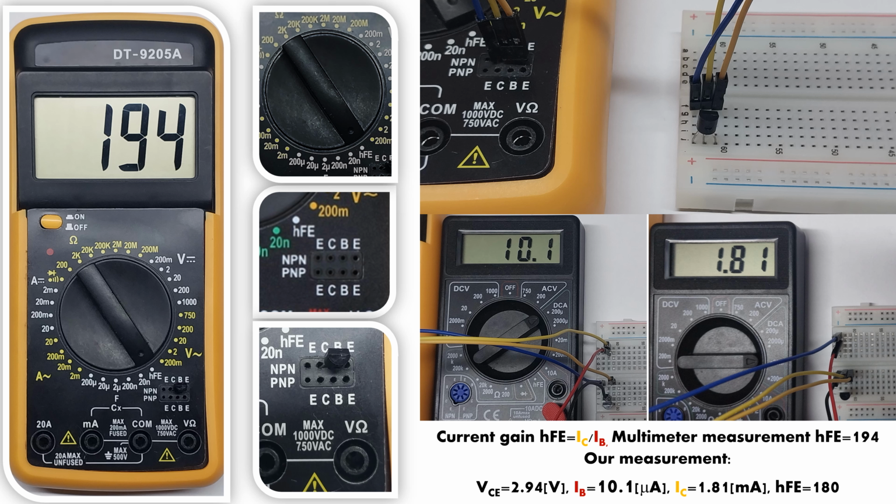In summary, to measure hFE parameter of a transistor, we use the hFE port on the multimeter, and choose hFE with the dial selector. Using the datasheet for a specific transistor, we identify and orient terminals, so they match slots on the hFE port on the multimeter. When the transistor is inserted, and the multimeter switched on, the display shows the measured hFE value. By means of replicating the hFE port from the multimeter onto the breadboard, we have been able to measure values for VCE, base current, shape of base signal, and verify our measurements by measuring collector current, and then calculating the hFE parameter, based on our measurements and readings.